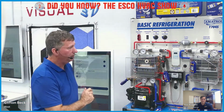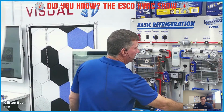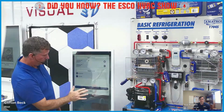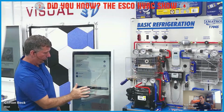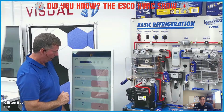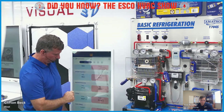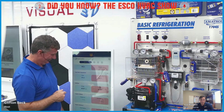Okay, and let's see. On this one, we'll be using the long ones. Yep. 9452. We'll be using that one. So this is broken between supply and return. Yep. Okay. And again, this is going to show you the relative humidity, dry bulb, wet bulb, and dew point. That's what's coming from the sensors. If you scroll down, it'll show you the enthalpy difference. Look at that. Okay. And we're using that to calculate capacity.